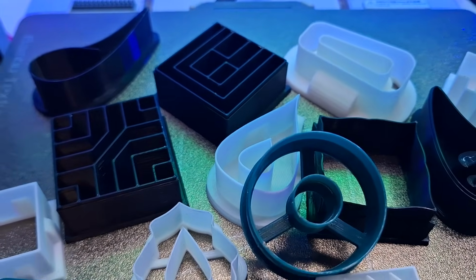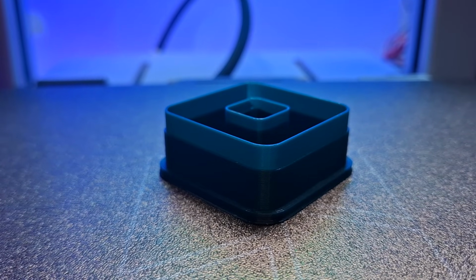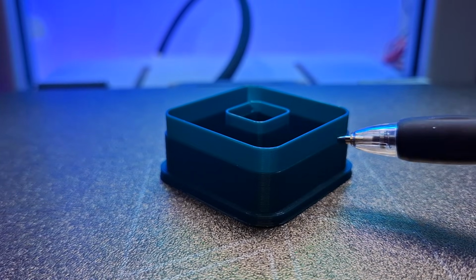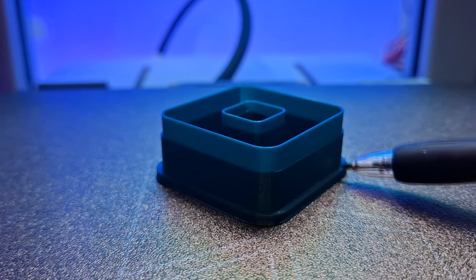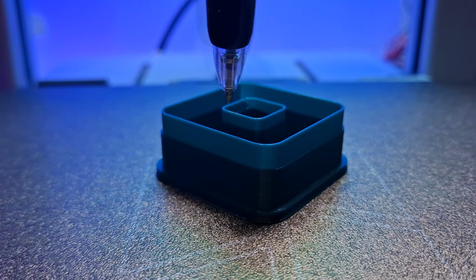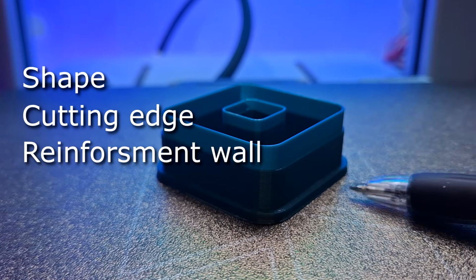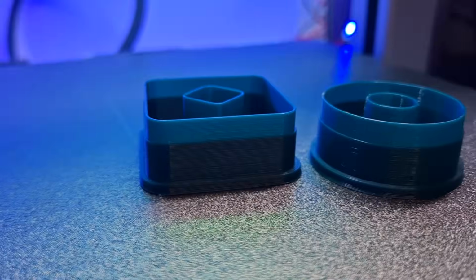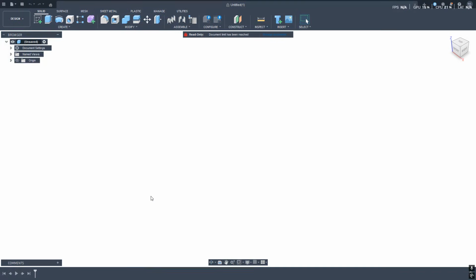Not a specific cutter, but a system. Now, when you break down a cutter, no matter the size or shape, every cutter is built from the same 4 parts. Once you understand these 4 parts, the design becomes very simple, and the shape almost doesn't matter anymore. These 4 parts are the shape, the cutting edge, the reinforcement wall, and the grip. Everything we do in Fusion 360 is building and controlling these 4 things.